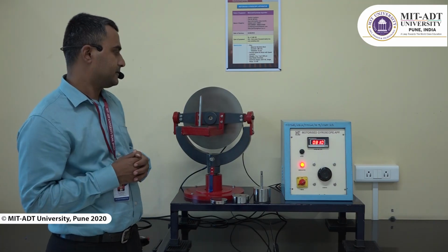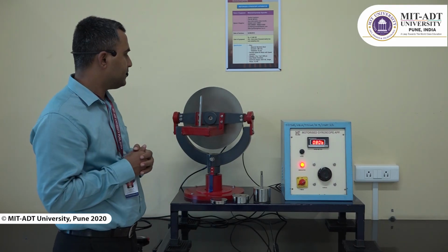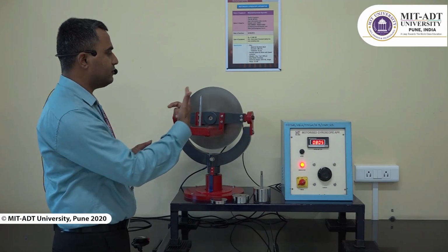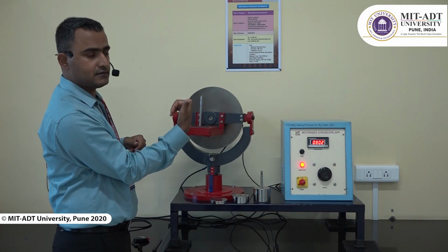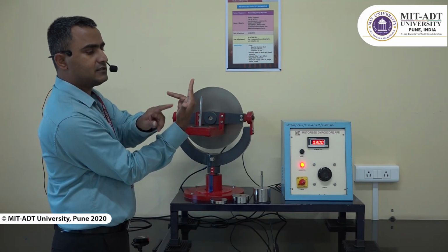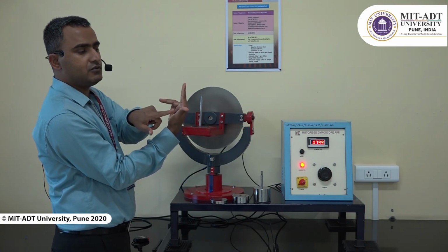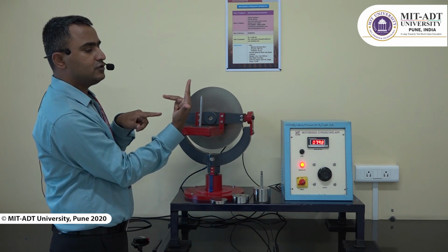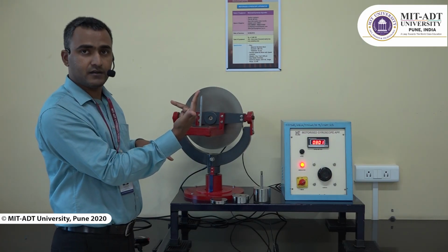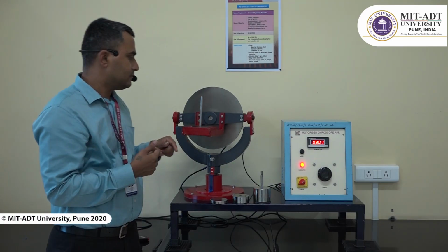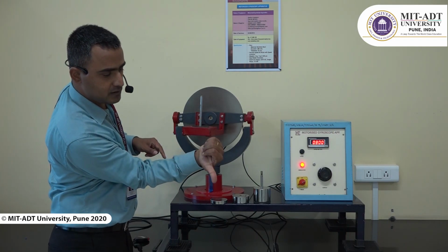Now, understanding the effect. I'll explain in detail the effect, where we have three mutually perpendicular axes. In this case it is rotating in anti-clockwise sense, and the axis of spin is here. So we have this axis of spin, this is the second axis perpendicular to the axis of spin, and the third axis is perpendicular to both of these. These three mutually perpendicular axes we are going to use to understand how the gyroscopic effect would be, since the rotation of the disk and the axis of spin is changing its position.